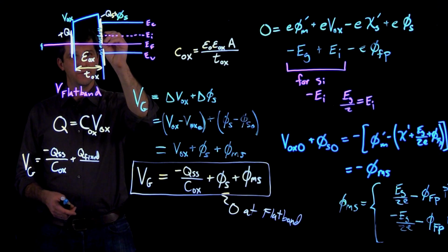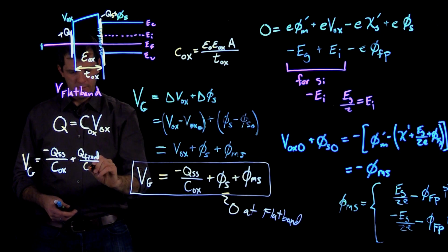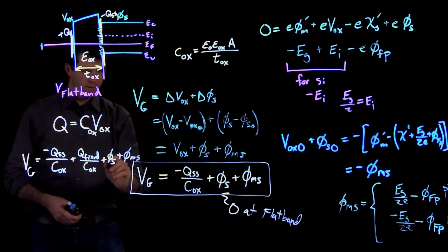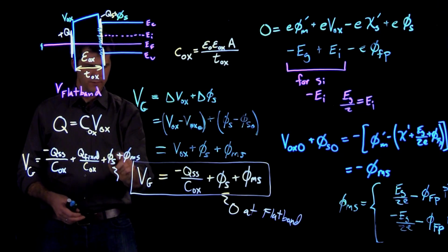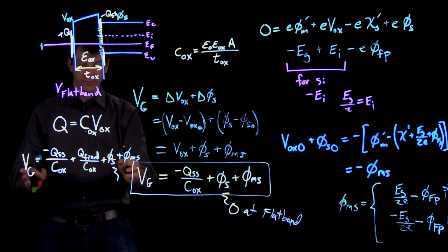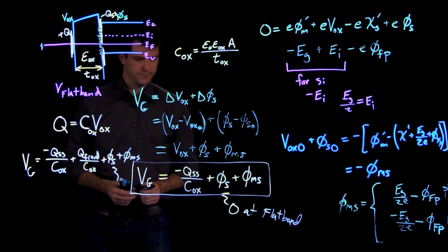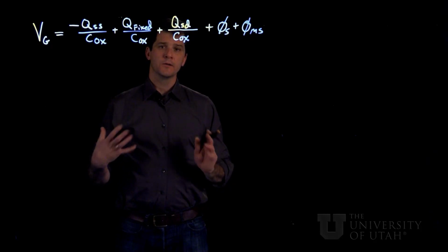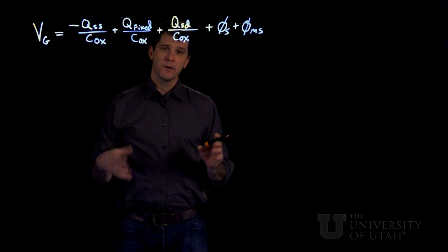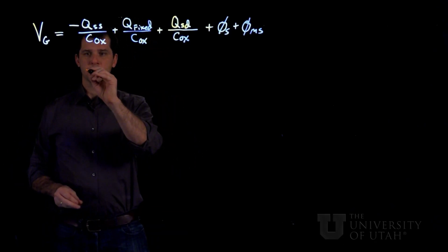Now these have to do with interface states or perhaps impurities formed right at that interface between the semiconductor and the insulator. And again, your flat band voltage will be where this is 0. And then you can see that the flat band voltage is going to be at a gate voltage which is changed by the presence of this fixed charge compared to the case without it. So there's one more type of charge density that we have to consider as we move through the 4 regimes of behavior of the MOS capacitor structure.